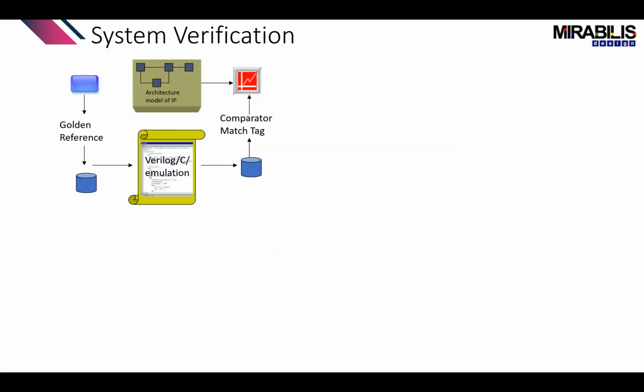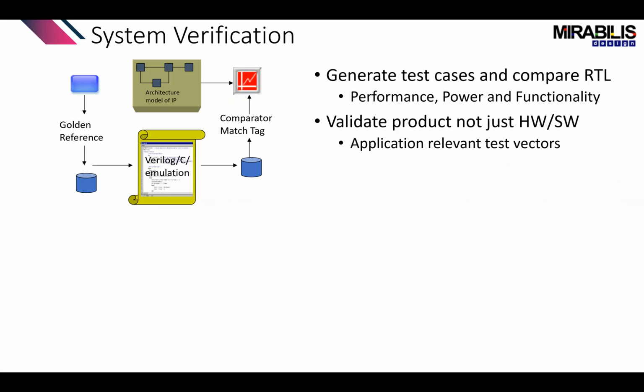Finally, system verification. Now, system verification is not just about connecting a top-level system model to RTL, but rather it's about what is the kind of data you need from the system model that can be reusable either for your C code, or it can be reused for your emulator or your Verilog code. So here the focus is primarily on performance and power verification.